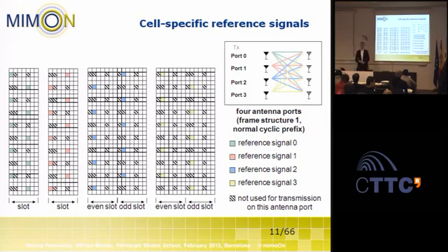So if we have 4 transmit antennas, the scheme is displayed here. We have 4 antennas with these time-frequency patterns of the reference signals. Again, we see that we have orthogonal schemes here. When one antenna is transmitting, the others are muted. We also observe that the third and the fourth antenna have a pilot spacing that is more sparse in time and frequency. This is to reduce the overhead from including these pilots. Of course, as I said, where pilots are transmitted, no payload data can be transmitted at that time and frequency.